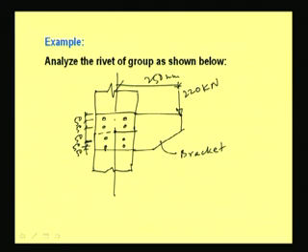So, the edge distance is 50 and pitch distance also is 50, and this distance is 60 and 60, this is also 60 and say this is also 60. So, in this way the rivets are placed, right.